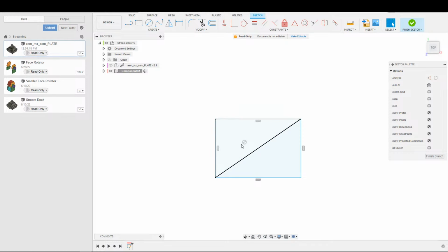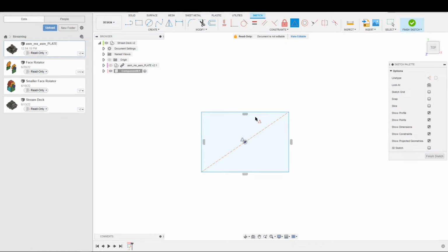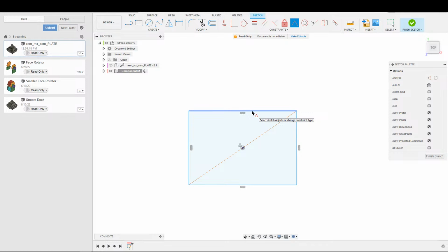So in that case, this area right here that we're defining can actually be the key switch spacing times, and I think I was going to do 9. That's what I said when we were talking about this. I'm just double thinking really quick whether or not I want it to be more than 9, because that would only be 3 inches across, which is quite small. Like, we can afford bigger is my thinking right now. If we can go to like a full 4 inches, that's still not taking much space. We get a bunch more buttons. That goes from 9 to 16 buttons, right? So the fact of the matter is that at 16 buttons, that may even be more than I'll ever need to begin with.